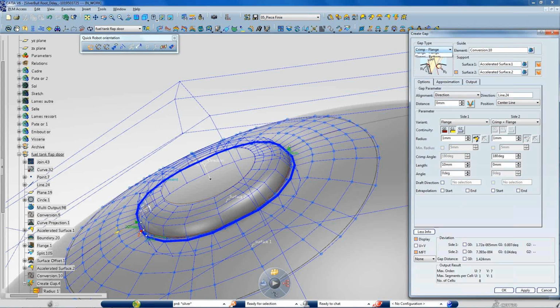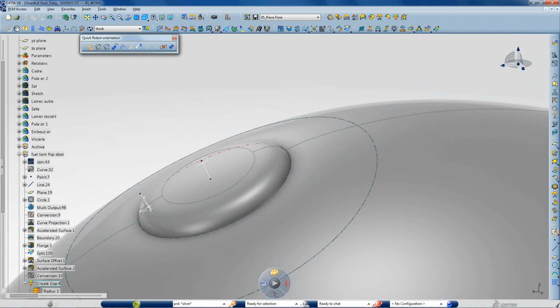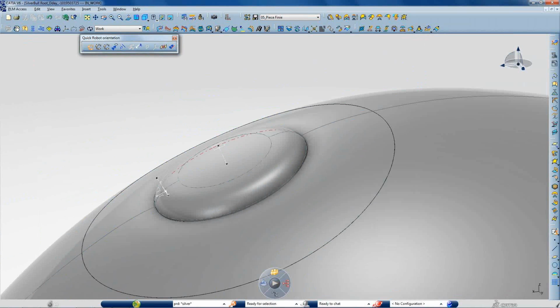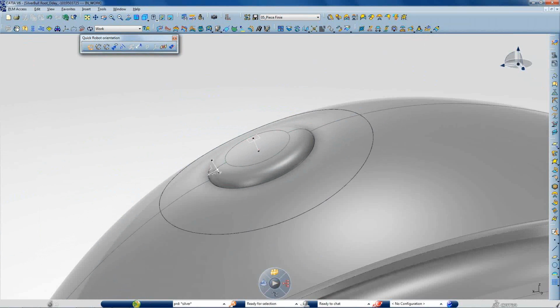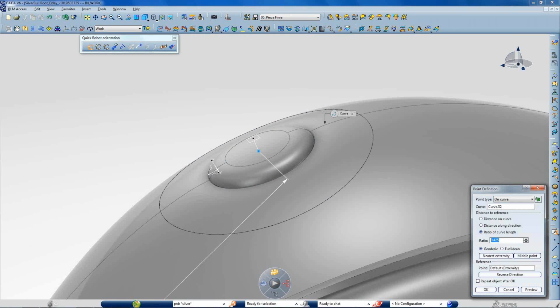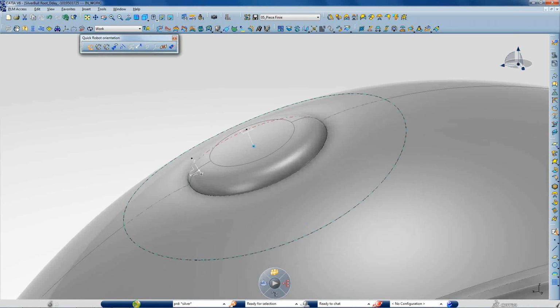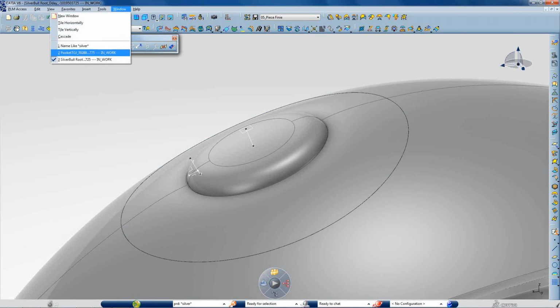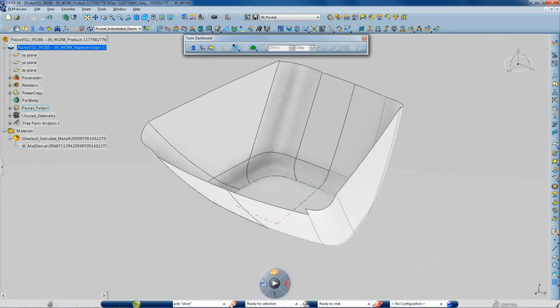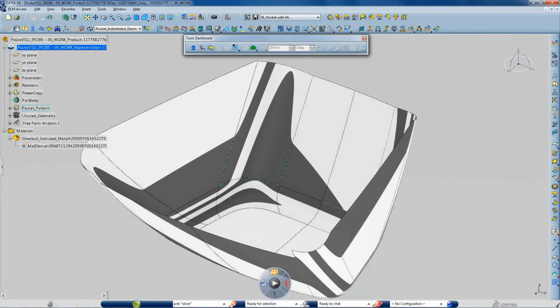Another example, between the cap and the fuel tank, we are creating automatically a gap feature that will automatically generate the fillet and the flange and do the stitch around it. And you can play with the value of the size of the gap, and you can see the regeneration of all the geometry. For example, here the designer made a modification, like changing the position of the cap, and this is where the feature-based associative approach is very interesting: if you move one of the constraints, it re-updates all the model. You don't need to rebuild all your Class A model.